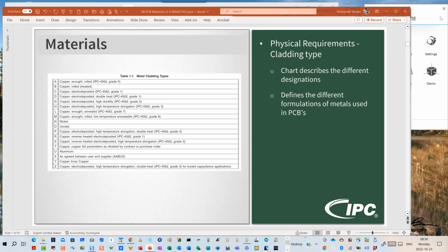However, on the other hand, under compressive loads like bolting actions, they are very soft and will now deform under compressive loads. So very good at tensile, very poor at compression. Wrought coppers are very good at compression, very poor at tensile loads. But in both of those cases, you have to start with solid materials, solid metals, right? Where electrodeposited, you can start with the metal dissolved in a liquid state so it can be deposited ion by ion, atom by atom, molecule by molecule onto the surface to a given thickness. It's kind of halfway in between.